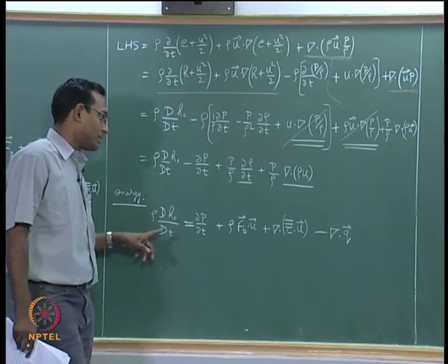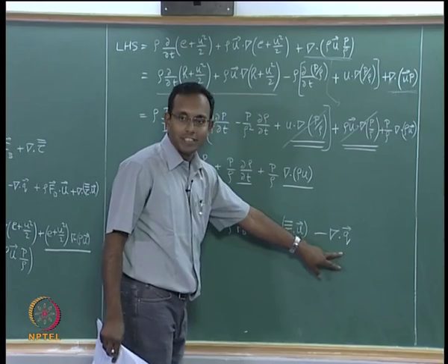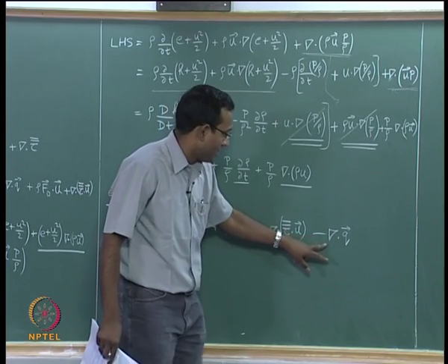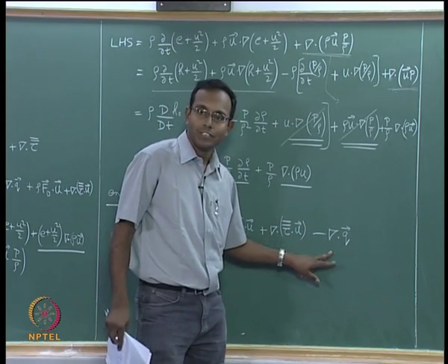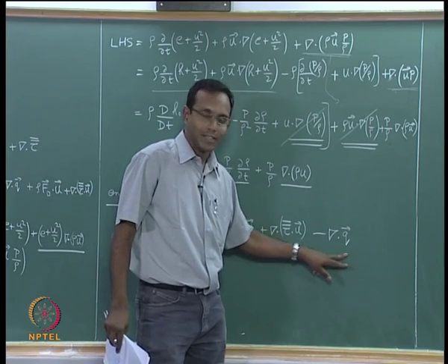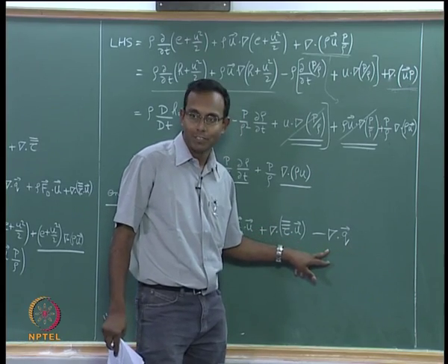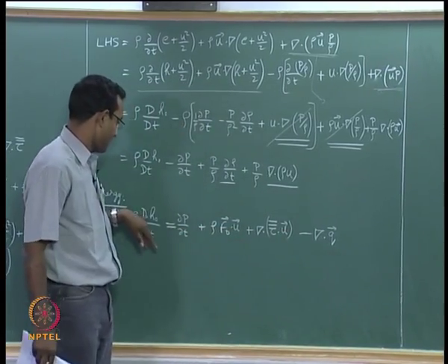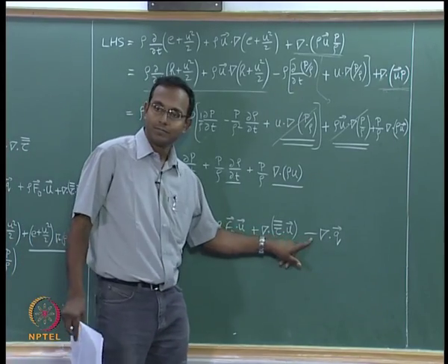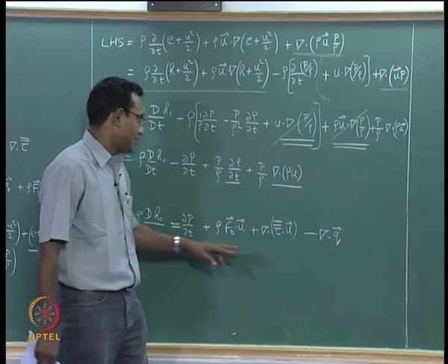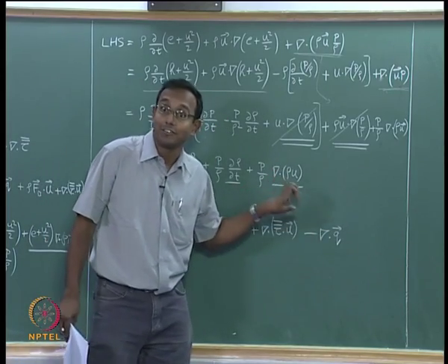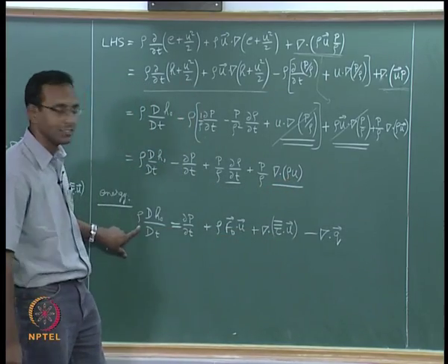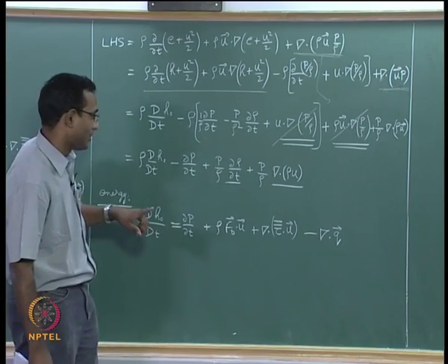If I look at it, it may change, the simplest term is this one, it may change because of, if I call it del dot q, the divergence of heat, this is heat conduction, heat flux q is basically talking about divergence of heat away from this point. So, if there is divergence of heat away from this point, that is going to have energy loss, so it is negative. Okay. Or you can think about it as minus of divergence is the convergence of heat, opposite of divergence, right, it is converging of heat into that point, that is increasing energy, whichever way you think about it. Okay. That is one term.